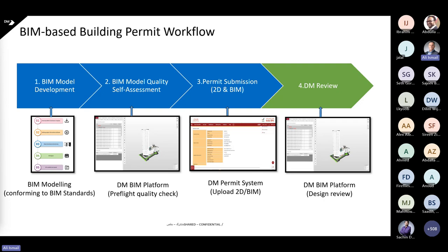Now, if we want to talk about the workflow, what has changed for a BIM mandated project? Actually, not too much has changed, because the consultant should still submit the 2D drawings as he used to, as he's familiar with. But the additional work by the BIM mandate will start by developing the BIM model itself. So in the BIM standard document, you will see the steps to create the BIM model. And we are going to go today, in a practical way based on a sample project, to explain how to prepare the BIM model.